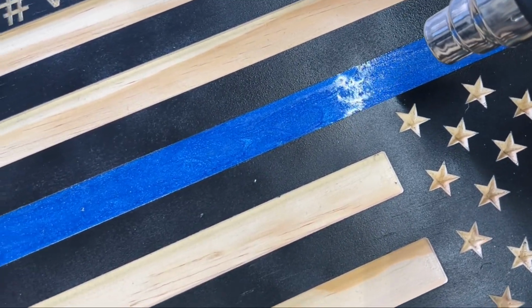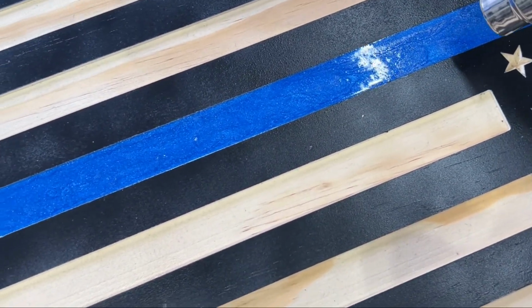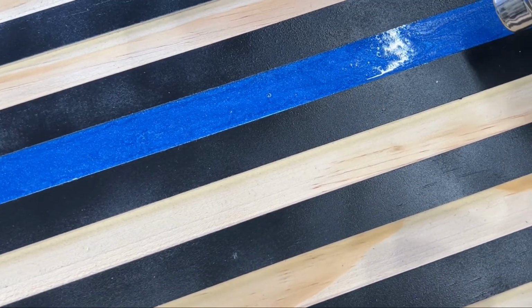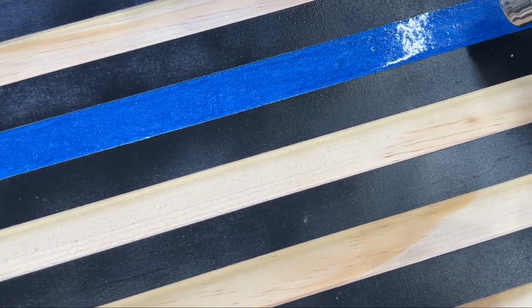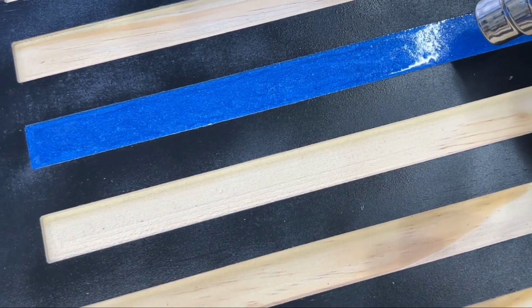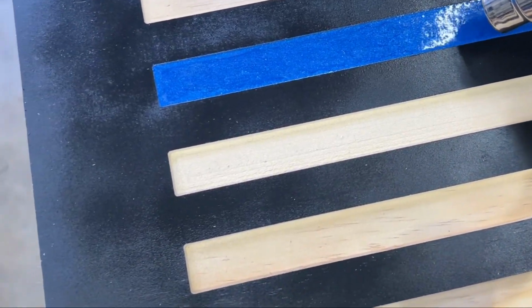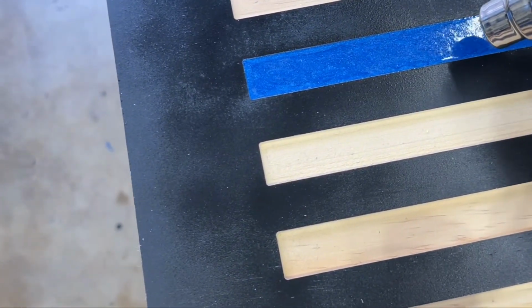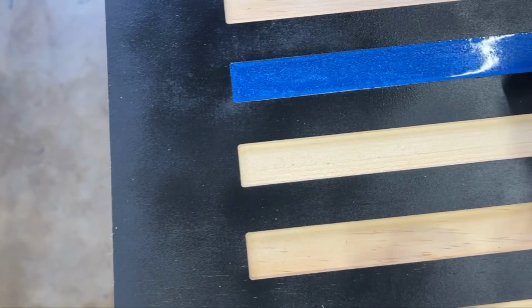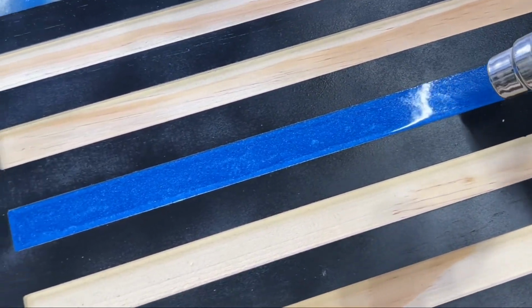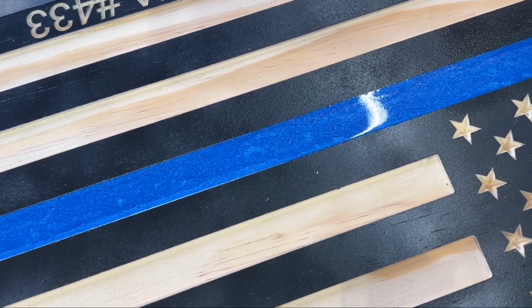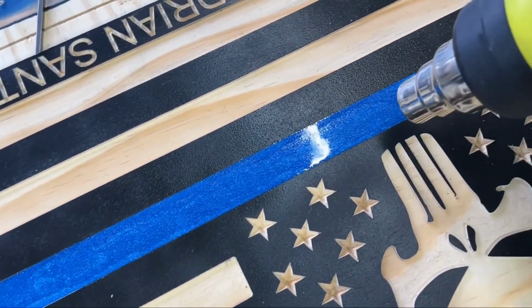You're going to see all those little spots, air bubbles. It's removing all the air. Leveling out the epoxy. That's it. I've seen a lot of people use blow torches and stuff, but again, not exactly needed because I don't want to mess up the paint and the clear on this. Like I said, I just go over it a couple times, get the air bubbles out.